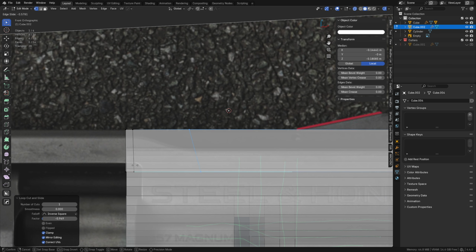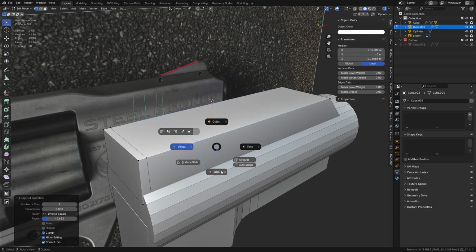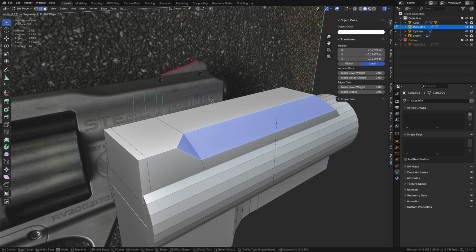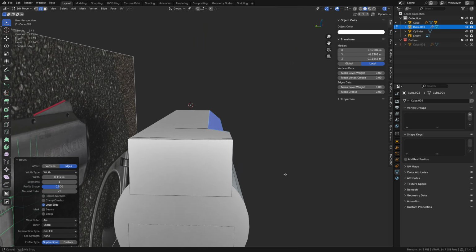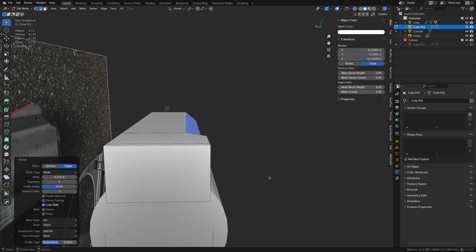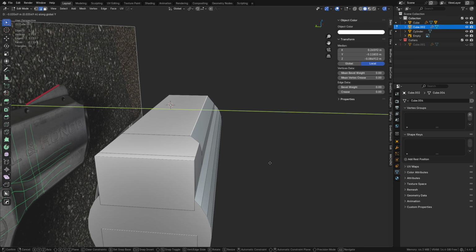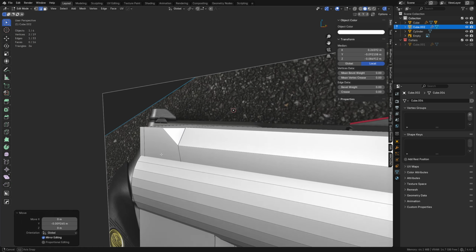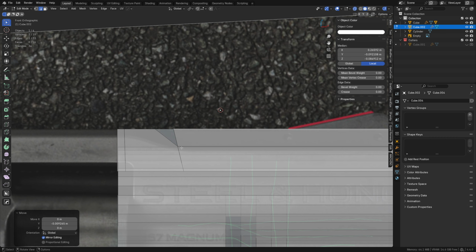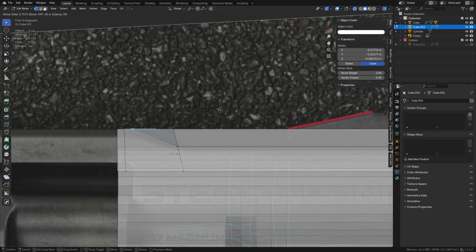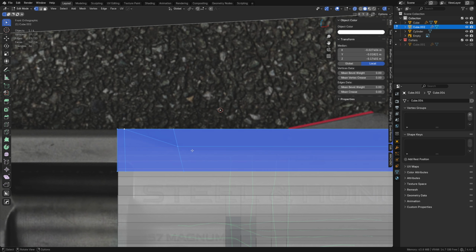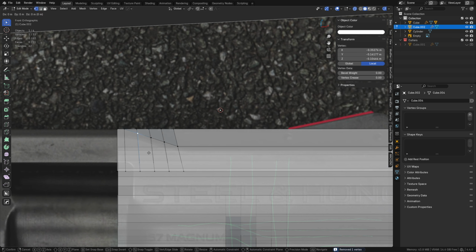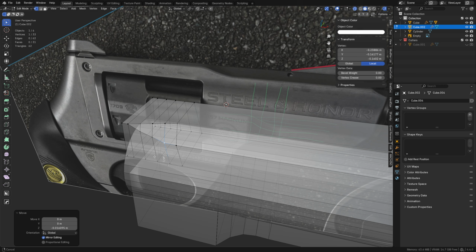Start and stop of it, usually pretty important. You can do like the chamfer, like that. And if you're not sure about the exact angle, that can be a little bit problematic, but you're probably going to move things. You're probably just going to G and Y them around. And you'll probably get it wrong, you'll probably have to redo it as well. That's just something that happens quite a bit. But you can see, we can start to work it out at least. So if we need, you know, 3 cuts in there or something, we can start to make this happen basically. And just kind of straight poly model it.